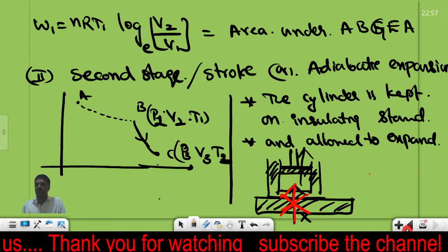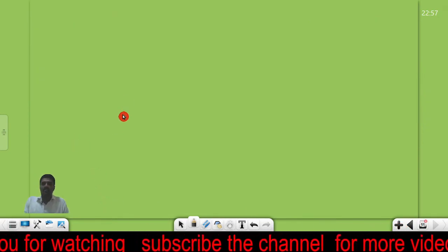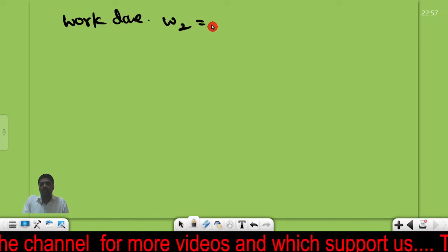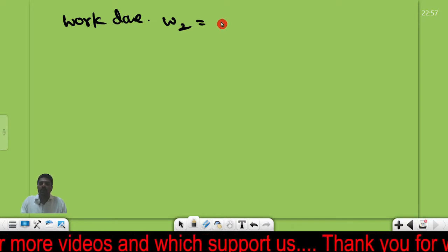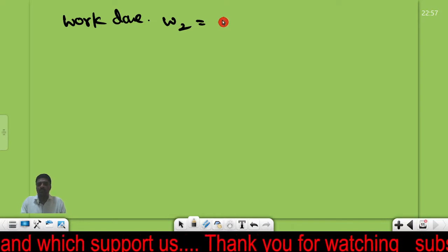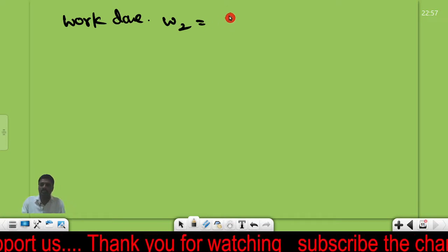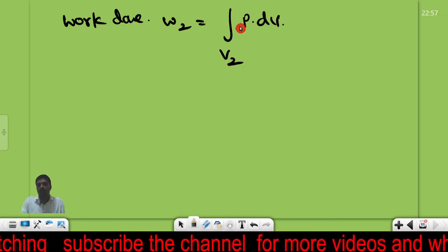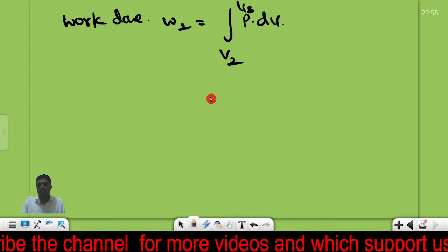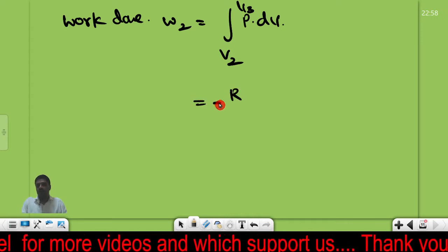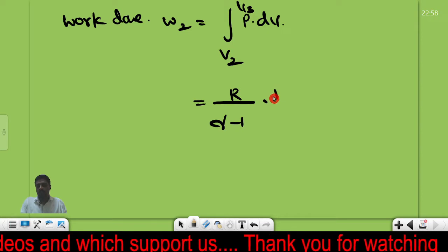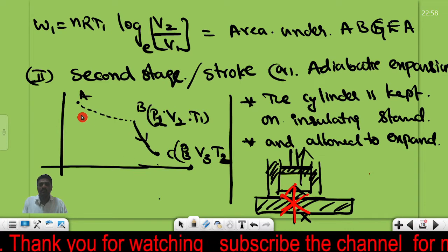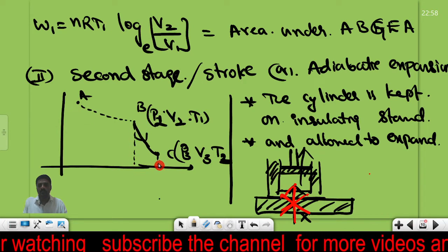Then what is the work done in this process? That is very important. Let me take the work done in this process as W2. I already discussed the work done formula in the adiabatic process. It is the integral of P dV, with initial volume V2 and final volume V3. This value we already discussed: R divided by gamma minus 1 into T1 minus T2. This formula is nothing but the area enclosed in this part.